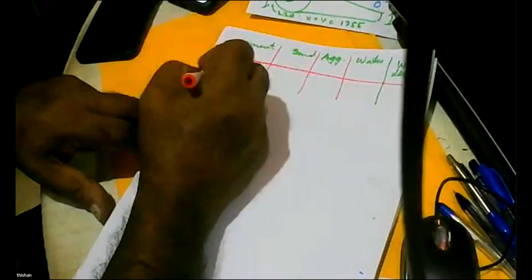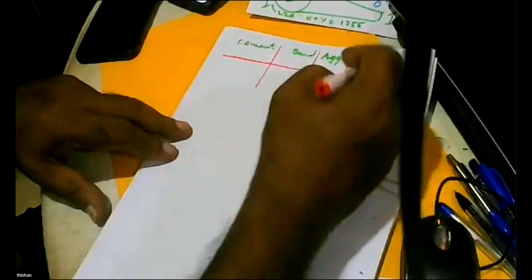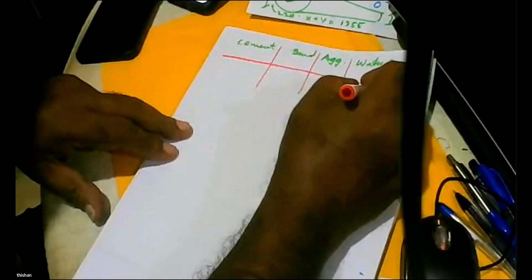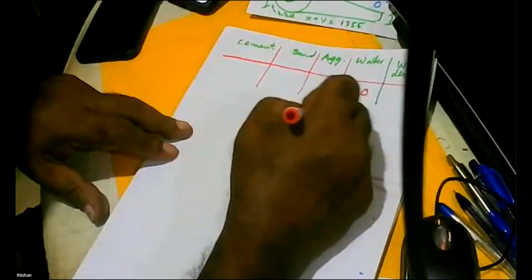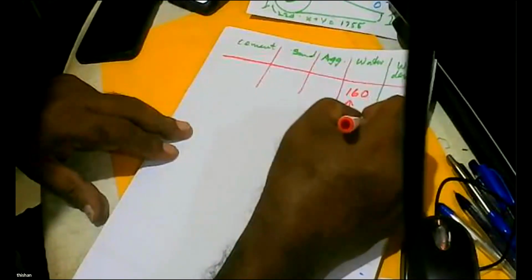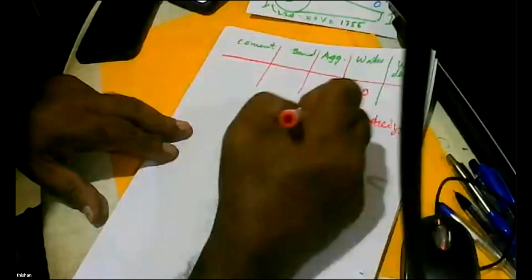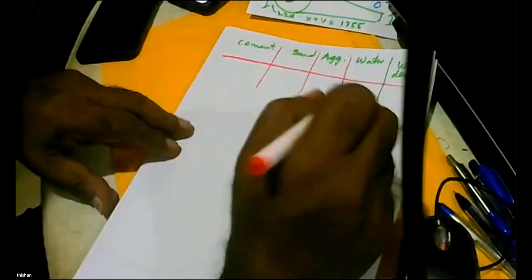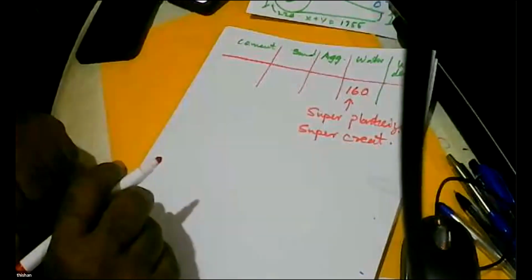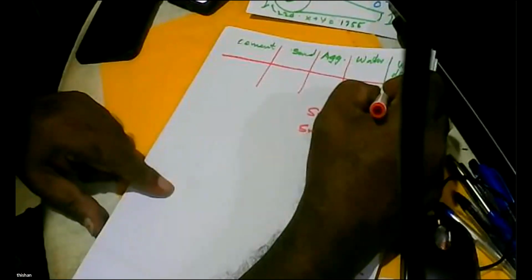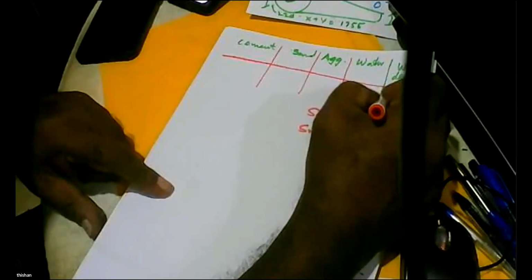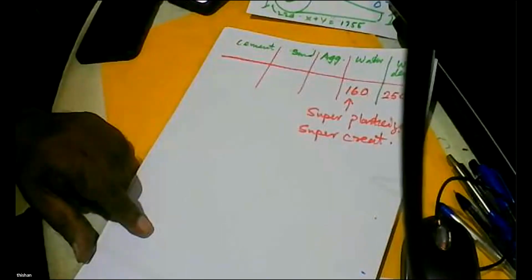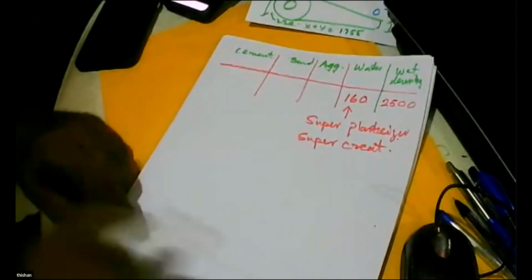It's okay. So cement. Now I'm going to use the admixture. So the first thing you enter is admixture. 160. So it's a superplasticizer, like Supercrete, created by Millennium Technologies. That's a trade name. And so density, as long as I don't use fly ash, density is 2500.